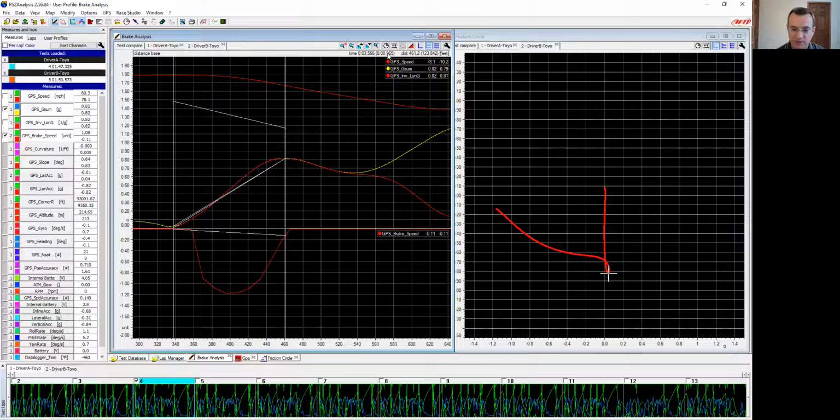The stiffer your springs are, the quicker your load transfer time is going to be. You don't have to wait for those front springs to compress and the tire to make full bite. But it's also possible on a stiffer chassis to quickly shock the actual tire and contact patch. So whereas on the Spec E30, we're waiting for the car to transition the chassis, on a more stiffly sprung car, you have to be concerned about shocking the contact patch and causing slip at the contact patch of the tire. So there's not a one-size-fits-all answer for everybody.